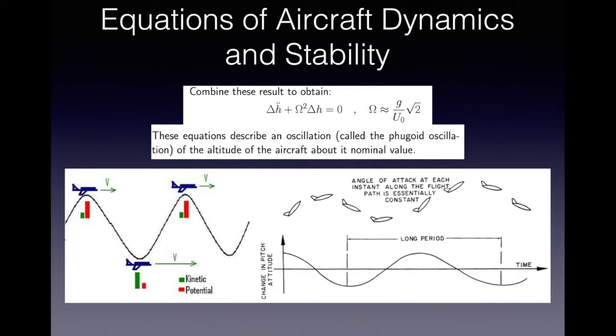It will detect small differences when at altitudes higher or lower than desired, then calculate and execute the required control surface deflection to bring the aircraft back to the set altitude. This can result in what is referred to as phugoid oscillation, which is where an object cycles between states of high potential energy and high kinetic energy, but the time average between these states remains relatively constant.